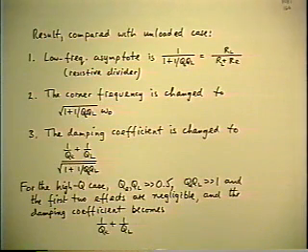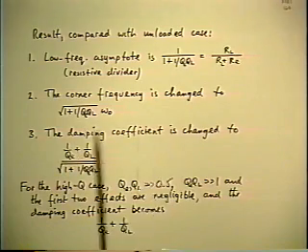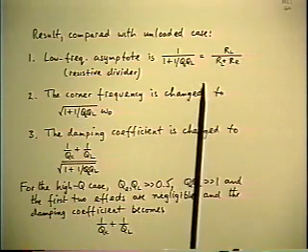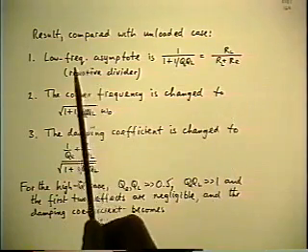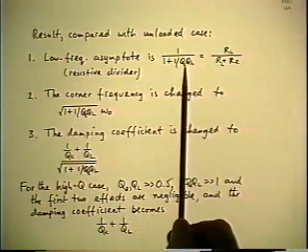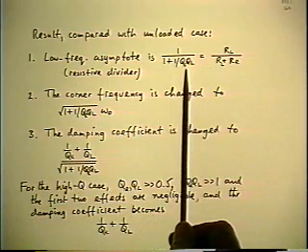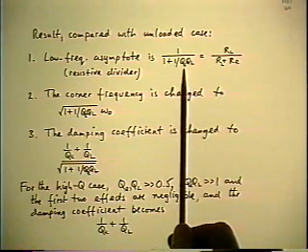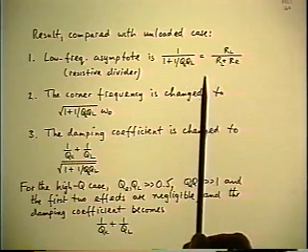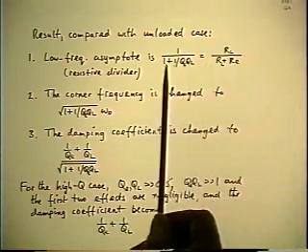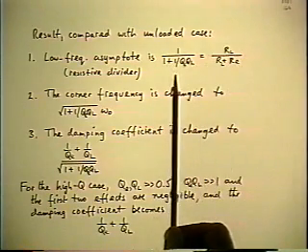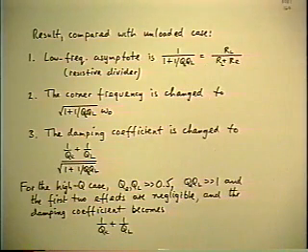Now you can extract even more information out of this result. In the context of a power supply filter again, dealing with a real inductor, you know what this zero frequency coefficient has to be. It has to be as close to 1 as possible. Because your objective is to make an efficient power supply, and the resistive divider effect of the LC filter is a direct factor in the efficiency.